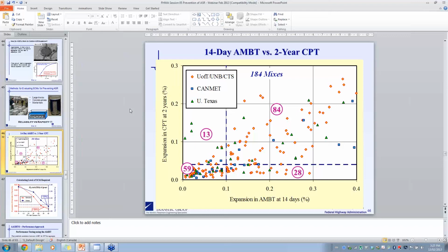The symptoms are different. Generally, if you've got cracks through you can identify reactive aggregates. If you've got cracks in your aggregates and you've got gel deposits in those cracks, the cracks extend down to the cement paste, you can be sure at least that ASR took a role, contributed.